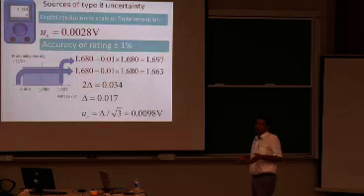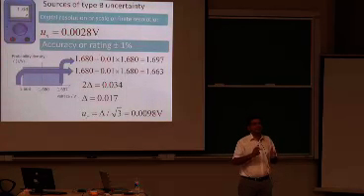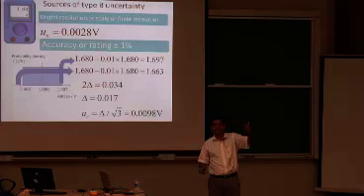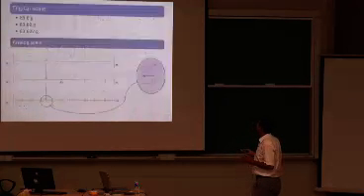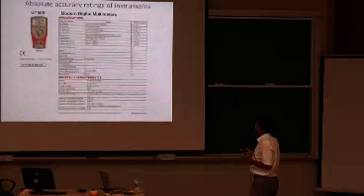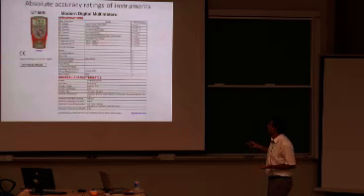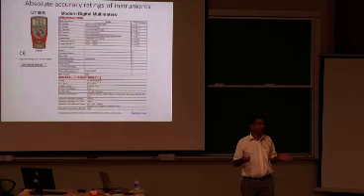Now the instrument can be inaccurate due to temperature fluctuations, due to internal resistances having a certain tolerance, and so on. So whenever an instrument is manufactured, the manufacturer provides a data sheet. Let me show you a typical sheet. This is a sheet that is provided by the instrument manufacturer. And in this sheet, they tell you what the best accuracy is. For example, if you measure in DC voltage, the best accuracy is 0.5 plus minus 1%.